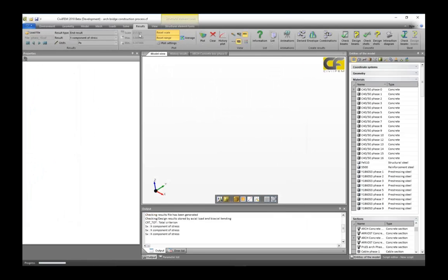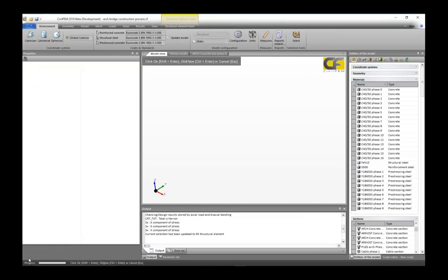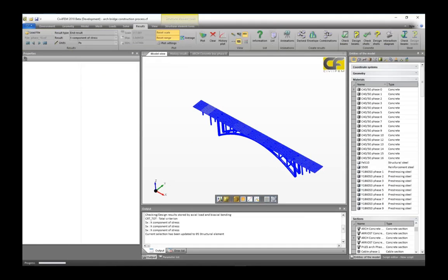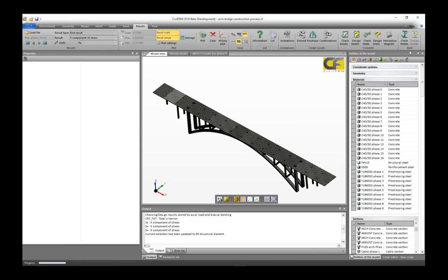The process is very similar to the steel elements that we have been performing in the steel structure. But in this particular case of the concrete, we work with reinforcement. So we can ask the software to check or verify the reinforcement that is added and defined, or we can ask the software how much more or less reinforcement we need to get an okay section according to the interaction diagram, which depends on the material pivots.